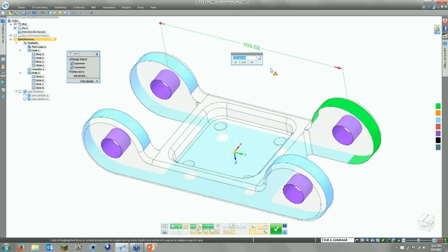All right, so what I just did is turn on my solution manager. This was previously used in other versions of Solid Edge. It allows you to look through the geometry and see if it's going to change, or how it's going to change, before it kind of happens. So you have this little color bar over here. It kind of gives you some feedback. Again, do you have to use this? No, you can always uncheck it so it doesn't bring it up. But what it does is interrogate it and tell you right now nothing looks like it's going to fail. Nothing is in orange. Everything is solvable, rigid.